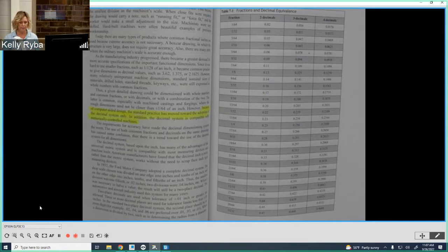Okay, so again, you're going to maybe see them. Probably the most common place where it's still okay is when we have fastener callouts that are to a fractional denomination, but we do not put any fractional values on a drawing.